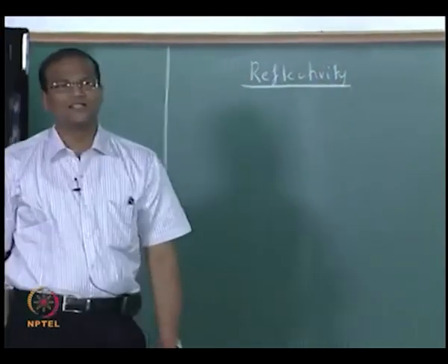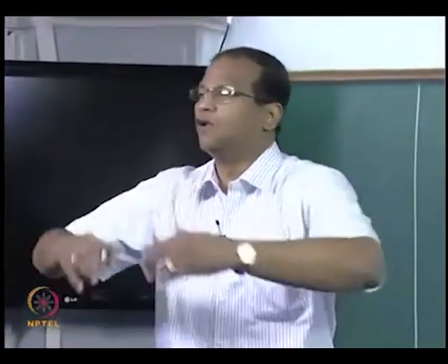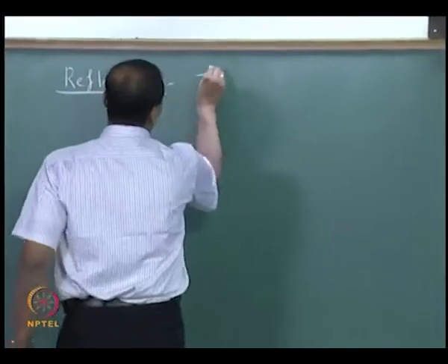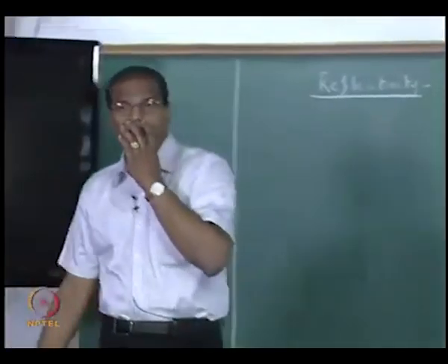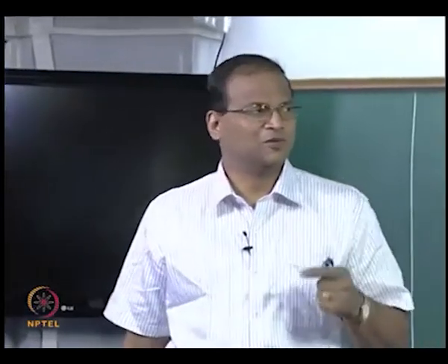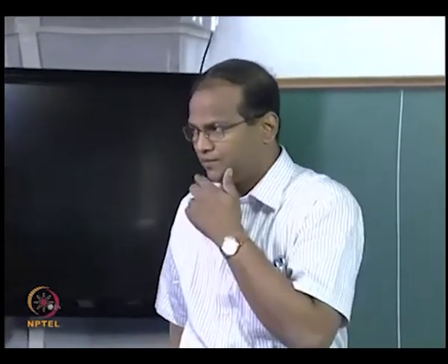As the name suggests, and also from past experience where we have already worked out problems with reflectivity given alpha, we assumed an opaque surface and then alpha plus rho equal to 1, therefore rho is equal to 1 minus alpha. So if I give you the distribution of alpha lambda, you can get rho lambda. You have calculated rho, that is reflectivity, and so on. But reflectivity is much more difficult than you thought. It is much more conceptually involved than you ever imagined, because